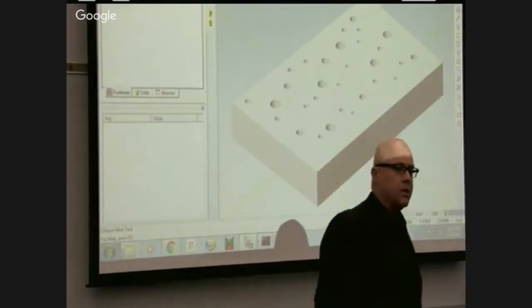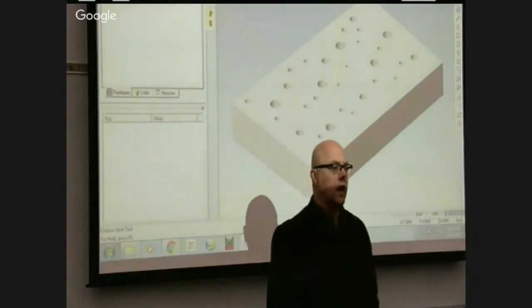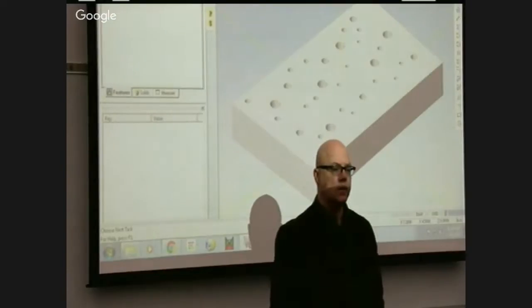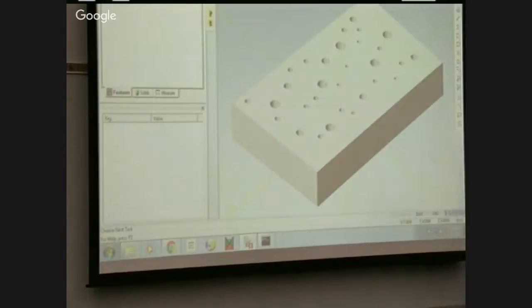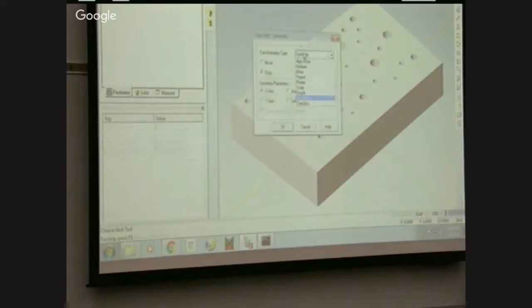And so what's the procedure to move the origin? How can we move the origin? Highlight the whole solid body. Say translate or go to copy. Translate. So I can select the solid. Right click. Copy. Translate. When you move, instead of copy, I want to move it.